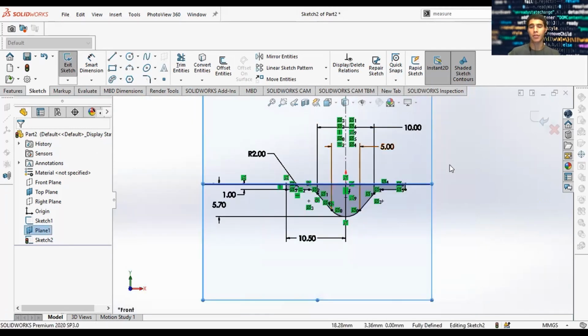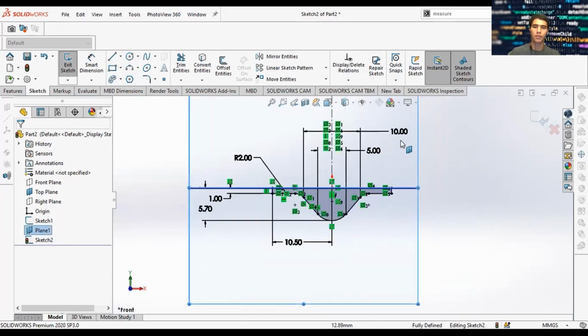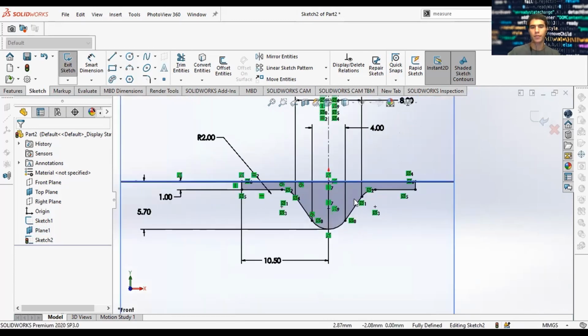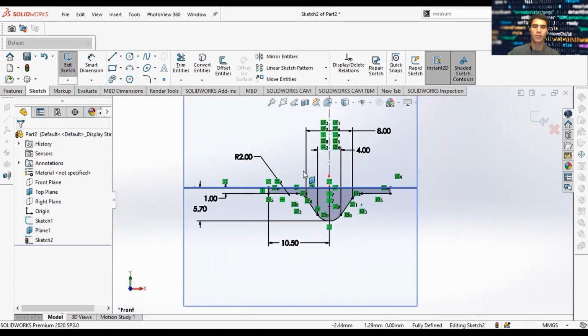Now you have fully defined the sketch, you can control the parameters within the sketch, which I think is easier. So now you can start getting more of that shape, like it is showing in the PowerPoint. Let's go with this shape. That looks nice. All we have to do then is click D on our keyboard and approve it, or you can go up here to this icon and approve it there.